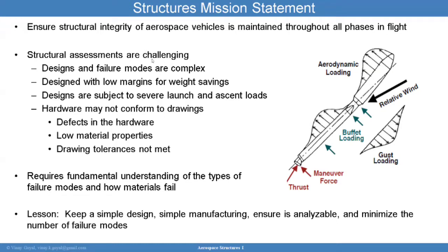Structural assessments are highly challenging. And why is that? Because, think about it. These are flying buildings, right? Designs and failure modes are quite complex. And I have to make them light. I have to make the structures light. They can't be too heavy because otherwise I can't fly them. And if I fly them, then maybe the payload that I'm putting there is just not going to be able to carry as much anymore. So the designs in general carry very low margins for weight savings purposes.